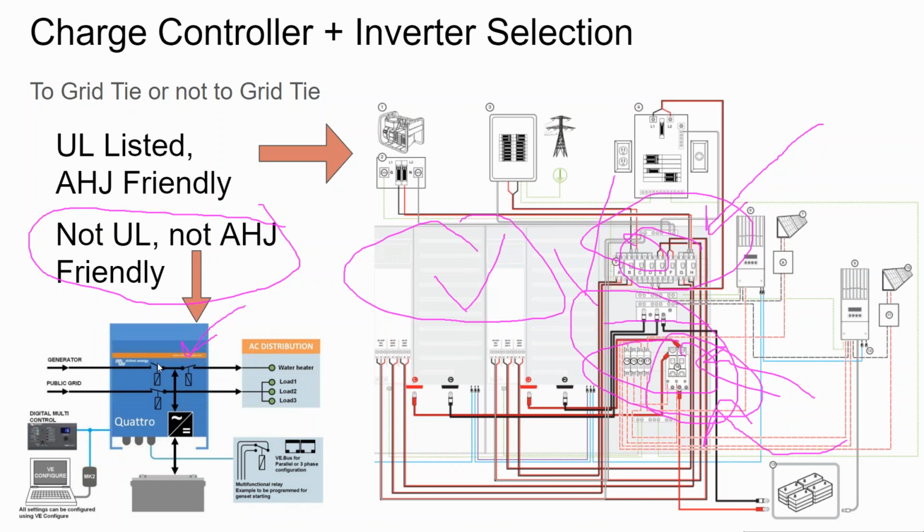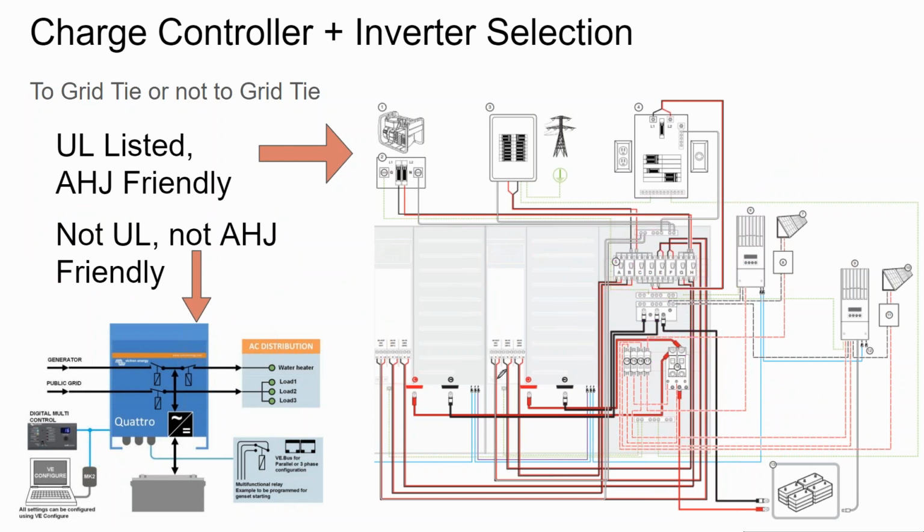But when you do your cost analysis, it's not just the cost of the inverter, it's also the cost of not only the specialty AC and DC panel, but also the cost of these specialty DC high amperage breakers, which you just can't go into Lowe's and grab off the shelf, because there aren't that many readily available DC appliances.